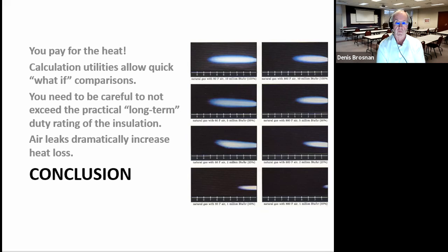And we're going to calculate the total amount of heat that you have to supply to heat up the material and to maintain the material for the soak period required for heat treating. It was a really simple example. Then the next class, we'll go to an example where there's an endothermic reaction that's pretty significant. In the last class, we're going to compare e-solutions with some real data that was taken in my laboratory. So that's where we're going in the course. There are going to be 3 classes that deal with the furnace simulation capability of e-solutions.